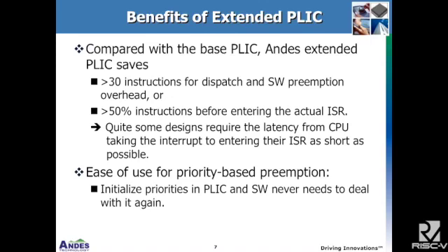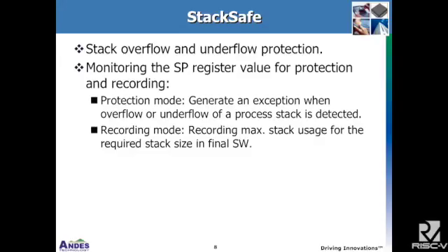And also another benefit is the ease of use for priority-based preemption. The programmer can just initialize the priorities for each interrupt in the PLIC, and then software never needs to deal with it again. And we also add a stack safe feature that will use hardware to do stack overflow and underflow protection. Basically, the hardware mechanism will monitor the SP register for protection.